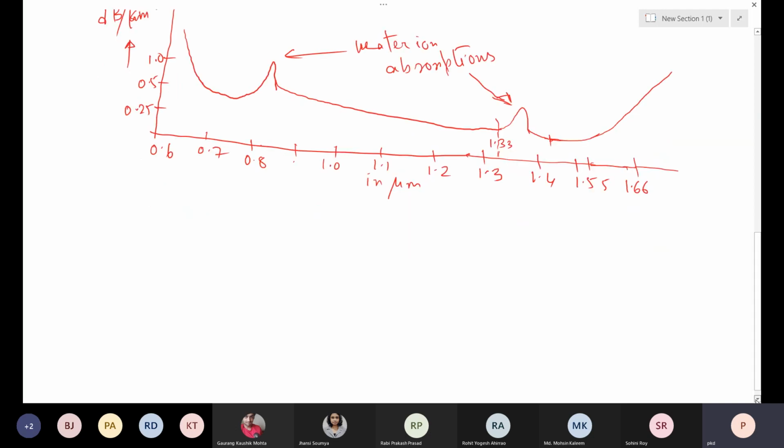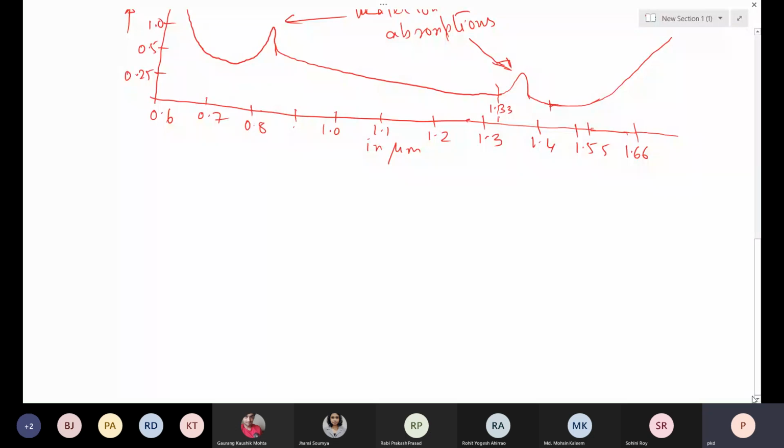So that's why silica-based optical fiber is so popular, because its low dispersion transmission zone is matched with the popularly available sources and detectors of III-V group, whose fabrication process is also very standardized. This side we have high frequency scattering, and this side is infrared absorption tail.